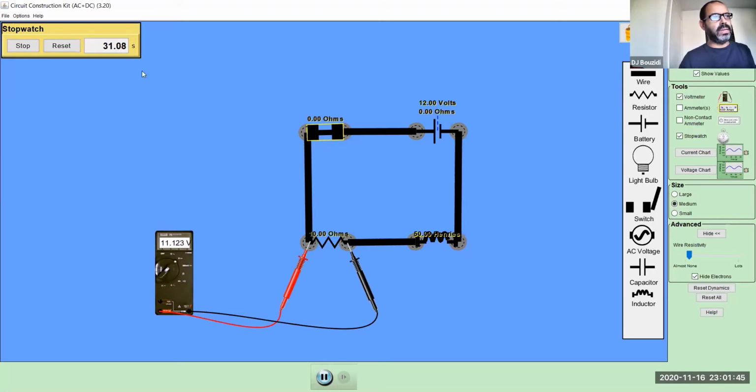So at the end, the time is still increasing super fast, but the voltage is hardly increasing. You're hardly going to notice it. But it's going to reach 12 volt and basically stop increasing. Right now, you will have to wait a long time to see an increase by thousandths of a volt. So this is saturation. That is the exponential growth that you saw. Initially, it's going to increase rapidly. That's why you need to catch it rapidly, okay? Otherwise, you're going to be dealing with the same values, and it looks like you have a constant function.